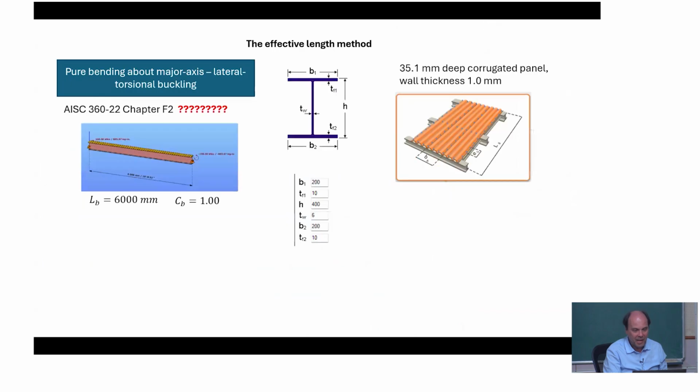And now what happens, for example, if we still stay with the uniform element, but we want to put a trapezoid deck? It's very often, for a metal building business, that it comes from the same hand: the primary, secondary structure, and also the sheeting. And of course, if the sheeting has some stabilization effect, why not take it into account to reduce the steel consumption? Obviously, it's not very rigid, but it has something. It's non-zero. Again, with the concept of stiffness matrix values, if I put something non-zero, it will have an impact. So why not try to do that?